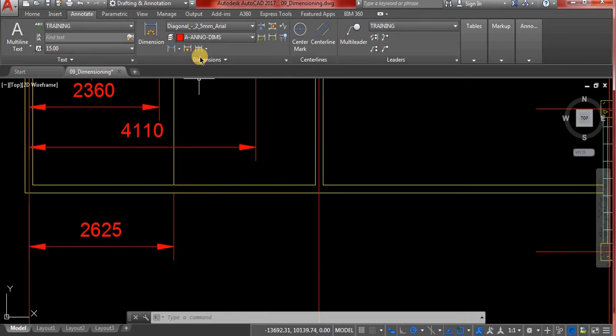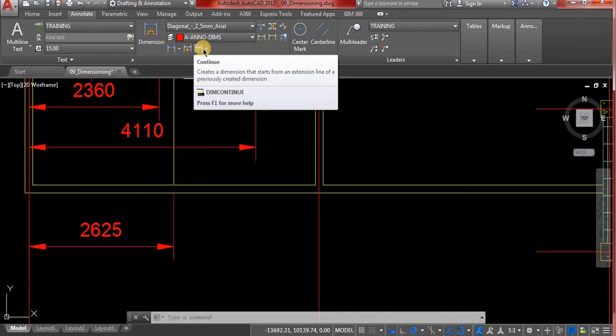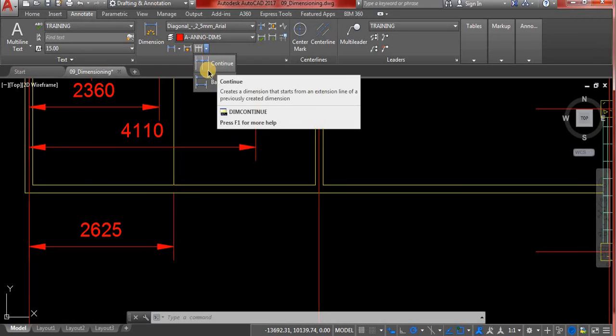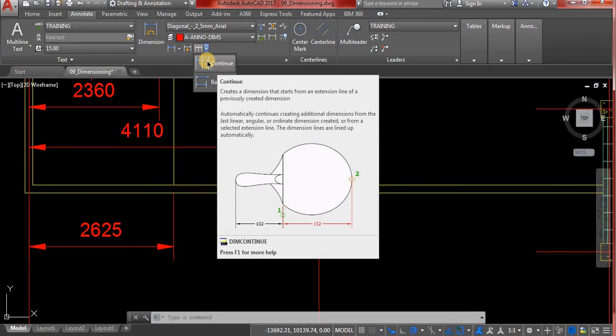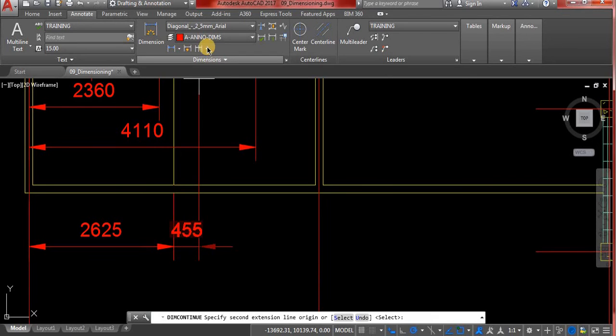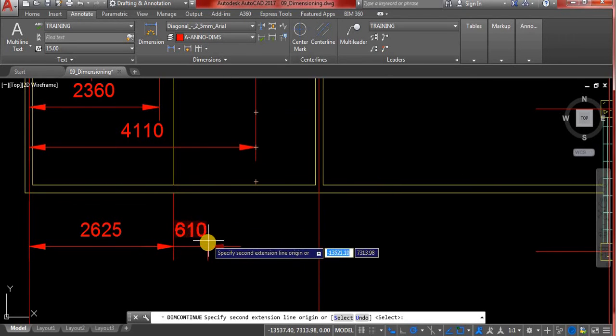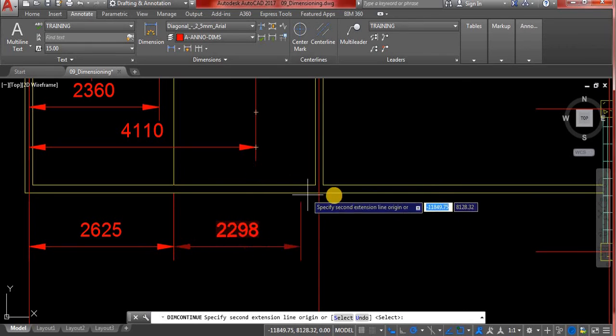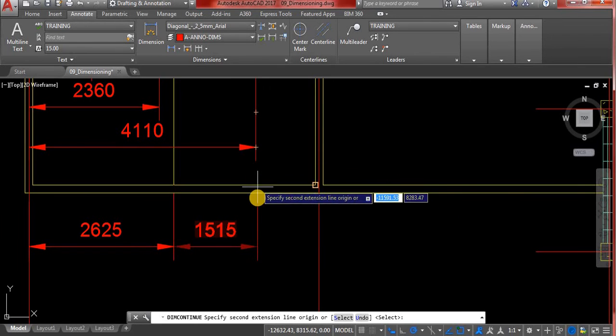so after that, you see, not the one beside it but the other one, there's an icon, continue a baseline. Obviously we want to choose continue, from the way I explained it and the example that I showed you. When I click on it, it snaps right away from this first dimension, and I can take it to any point that I want. Maybe snap it to this dimension.